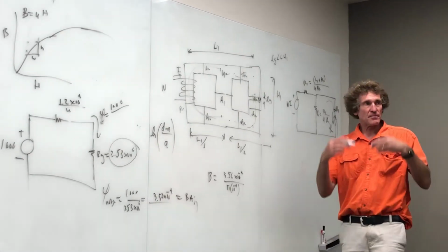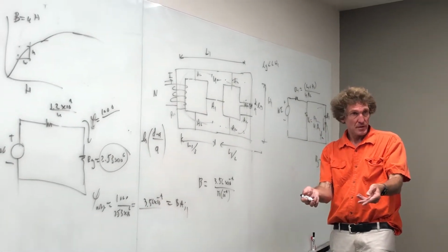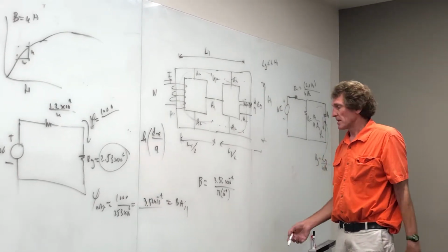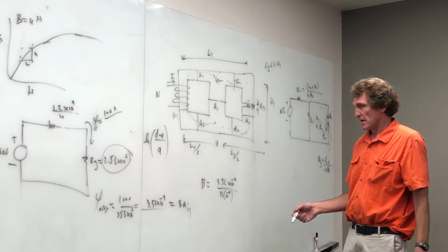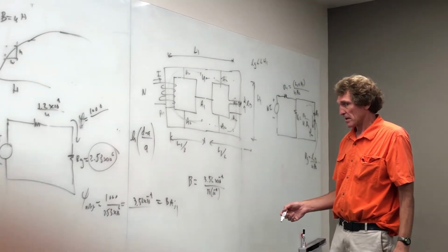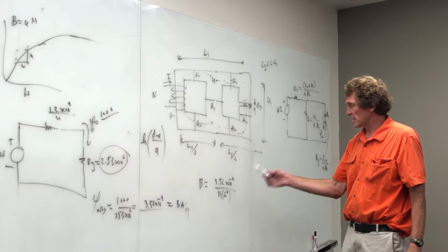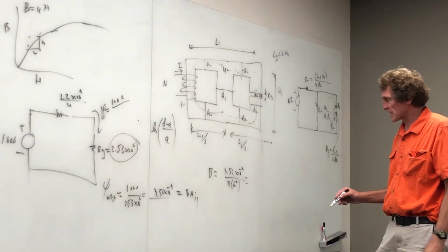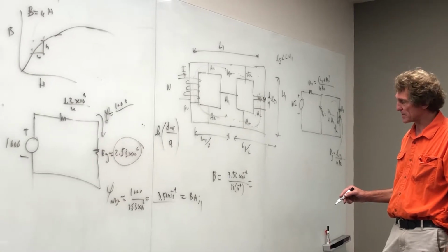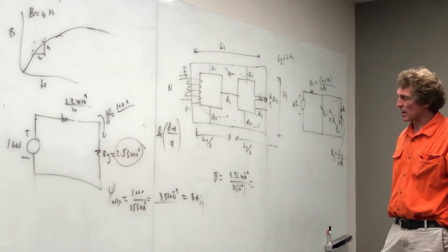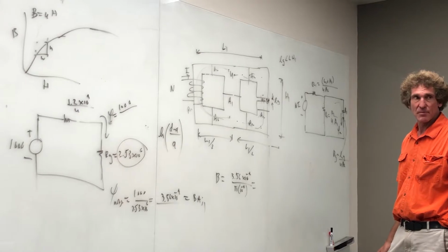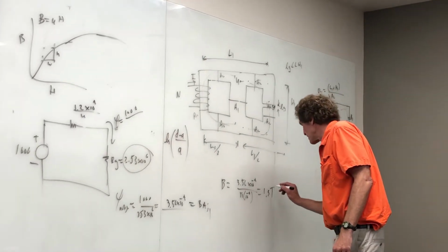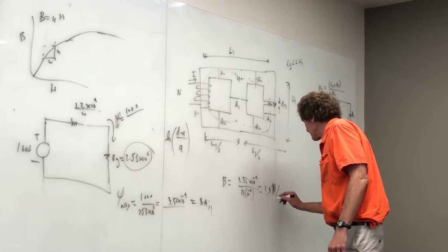I know the B field divided by mu would be the H field, right? Correct, class? But for now, let's calculate this B field. What do you get for this? The 10 to the minus 4th cancel, so I get 3.56 by pi. It's about 1.1, something like that, 1.2? 1.3? That's 1.3 Webers per meter squared.